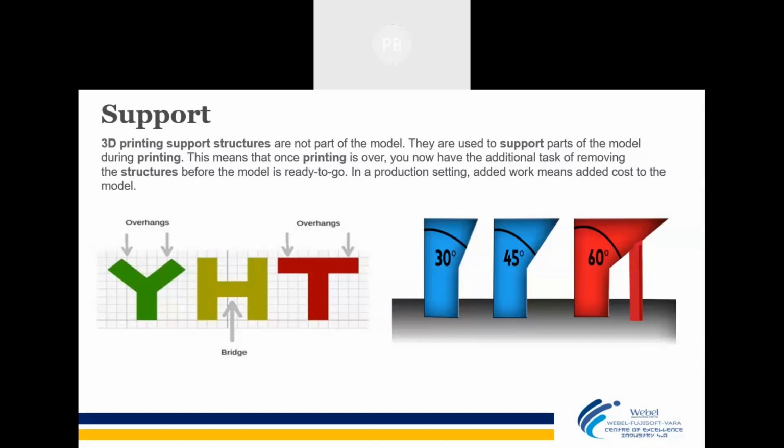Just half of it. So it will be around 100 layers. So by depositing 100 layers, I am getting the same model of 20 mm, but with a 200 micron layer height. The difference will be that with 200 micron layer height, my model will obviously print faster. At 100 micron layer height, my model will print at a much slower speed.